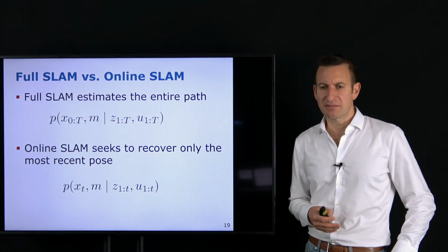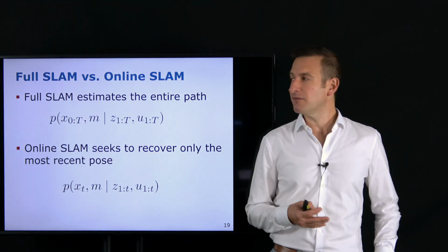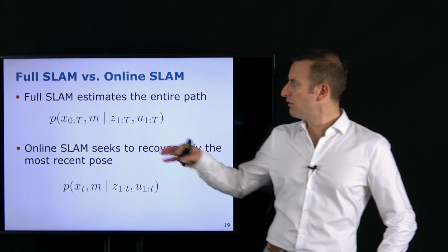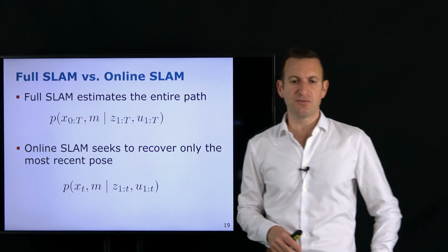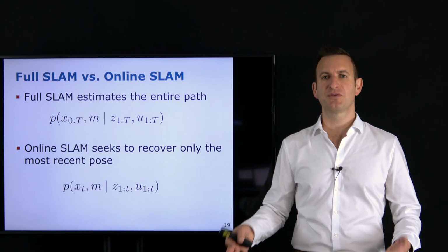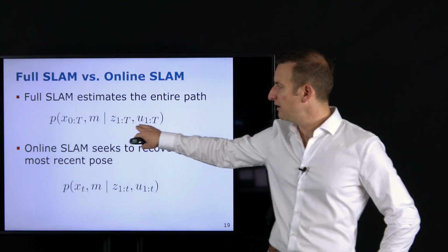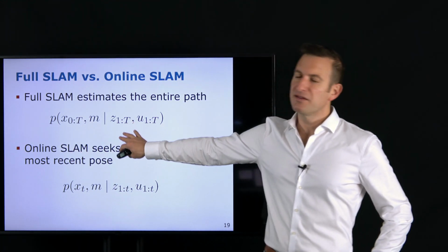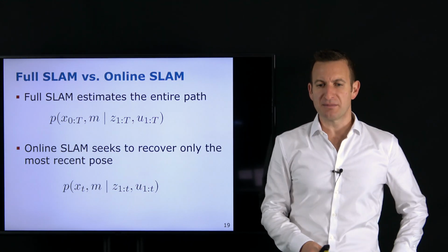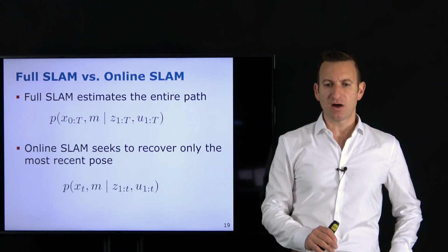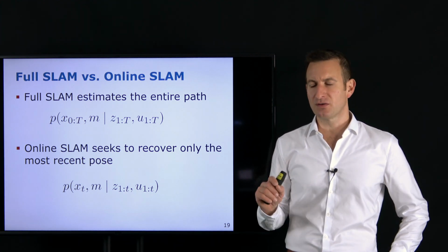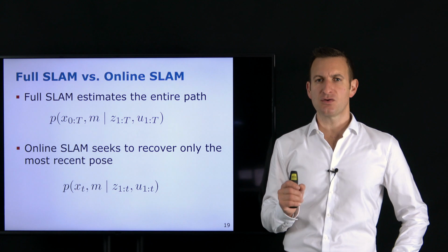I talked before a little bit about SLAM, online versus offline SLAM. Instead of offline SLAM, we also often use the term full SLAM, where we want to estimate the full SLAM posterior. This led to the term full SLAM, which was the posterior that I actually showed over here. And this has a more direct relation to the bundle adjustment problem. In online SLAM, however, we are only interested, or most of the time only interested, in the current estimate.